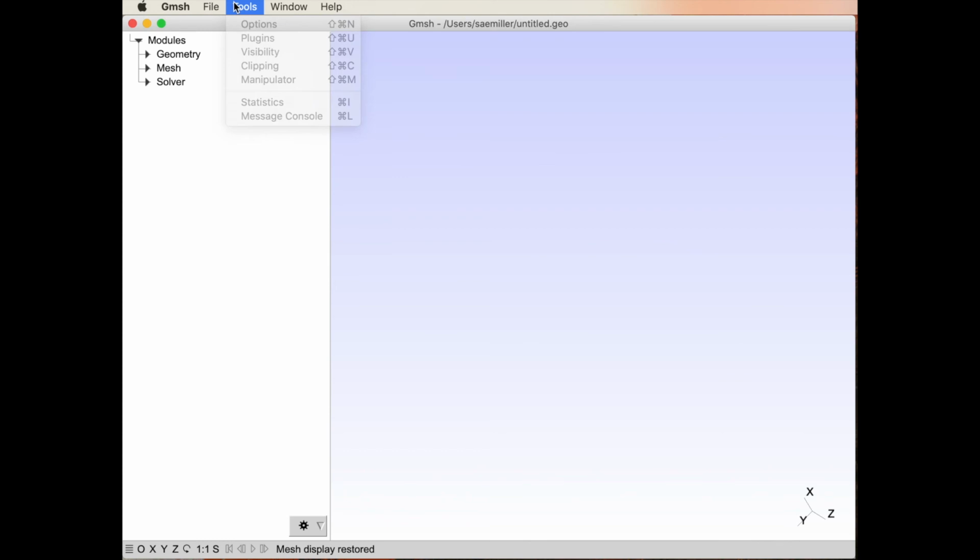So I don't see that in here. There's not like edit undo. And that's because the amount of memory a mesh generation solver uses is tremendous. And so it can't save previous meshes and mesh operations. And so if you mess up, it's easier to load a previous mesh than it is to redo everything. And so get in that habit right away.